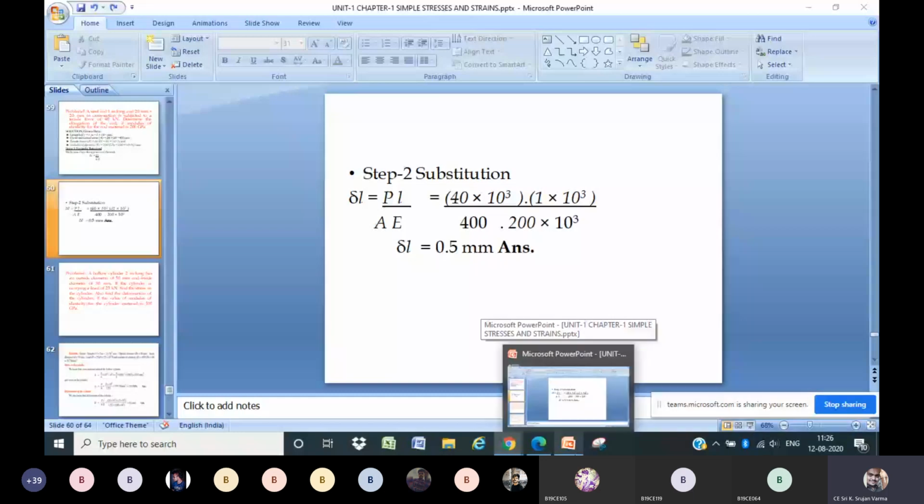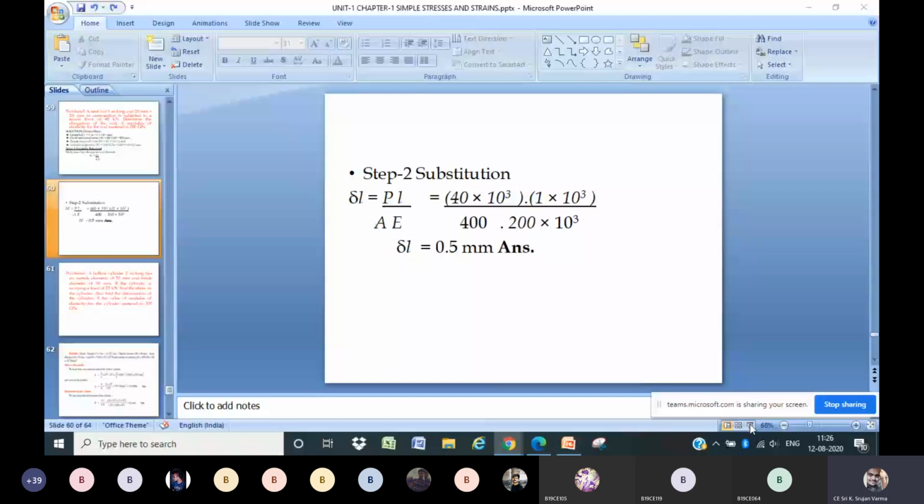So I'm directly substituting the values here. 40 into 10 to the power 3 multiplied by the length, 1 into 10 to the power 3, that is 1000 millimeter, divided by the area, 400 multiplied by 200 into 10 to the power 3. So I got delta L, the change in length, which is equal to 0.5 millimeter.